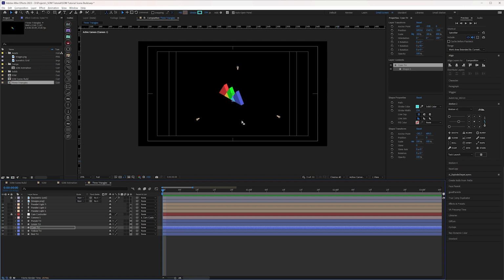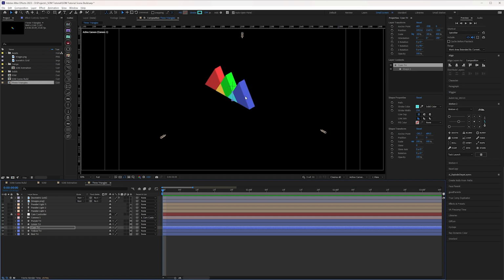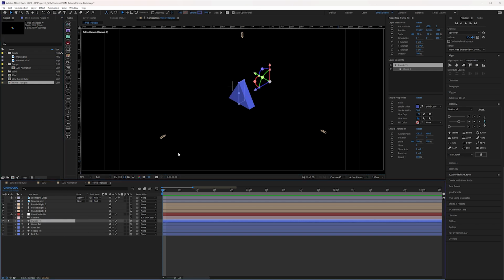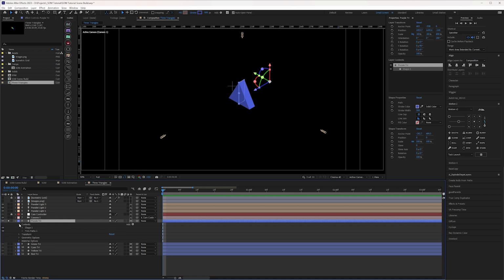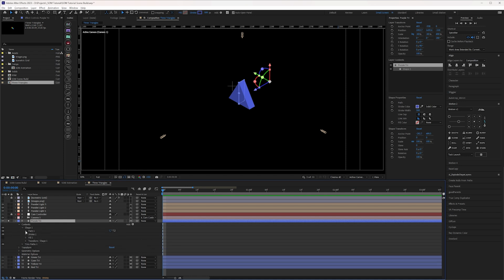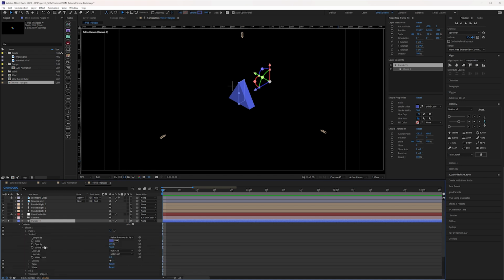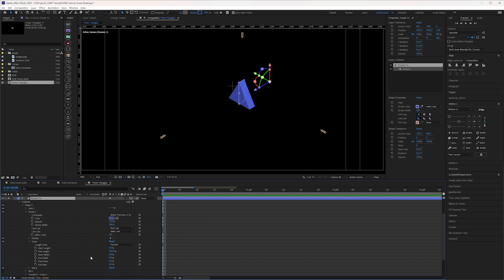Now let's try to build the three triangles of School of Motion. For this part we can use a stroke, but a tapered one. Let me explain what I mean. So this is a usual stroke from the ones we did, but here in the stroke we enabled the taper and made the end length 100. So this gives us the triangle look.